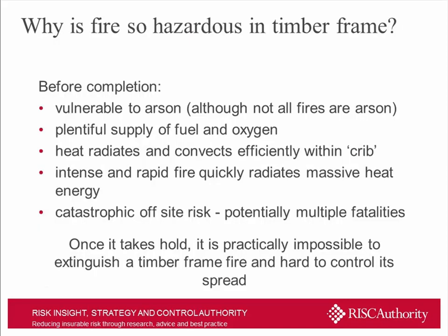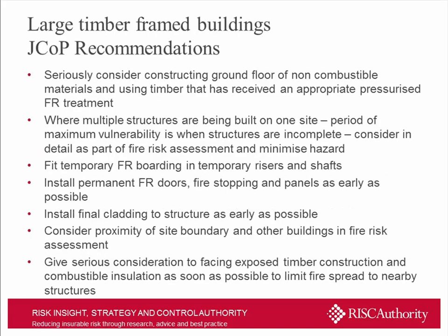So why are fires in timber frames so hazardous? Well, they're vulnerable due to arson, although not all fires are arson. Plentiful supply of oxygen, heat radiates and convects effectively within what is a timber crib. It's intense and rapid, so it can escalate very, very quickly. And there's a significant off-site risk, as we've seen in a number of circumstances, including the fire that happened at Aerodrome Road in Colindale or Hendon. And once it takes hold, it can be significantly difficult to put it out.